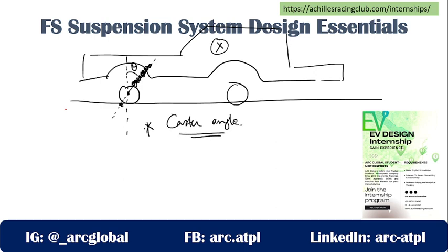This particular angle is very important because it has the most influence on the turning force, turning moment, or the cornering force that is needed to corner your vehicle. Caster is the most important phenomenon in your vehicle when you are designing the suspension system or the steering system.